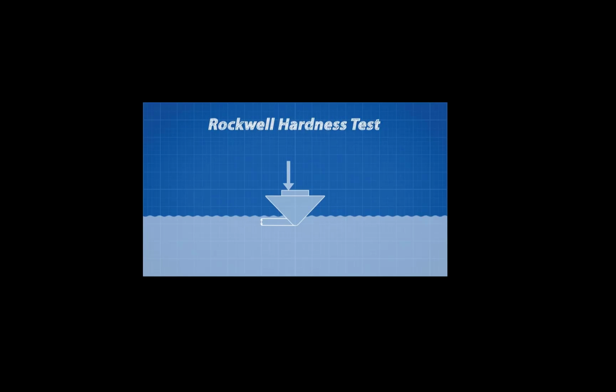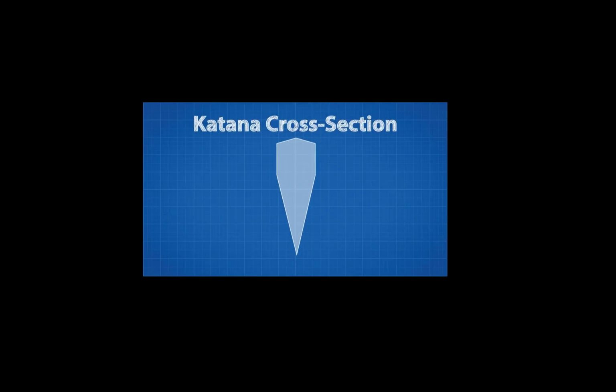Diamond is a very hard material, which is why it is used in cutting tools. One of the fantastic properties of steel is its ability to be heat treated, to have its hardness tailored in different areas. For example, with swords you want your cutting edge to be hard, but the core of the blade to be ductile. This means the sword can bend under pressure without breaking, while the cutting edge can resist damage.